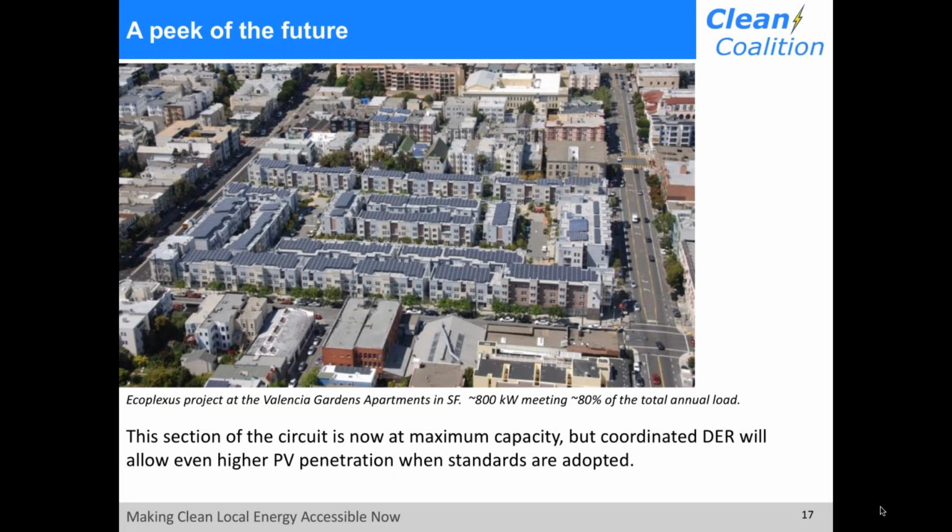Under a separate CEC grant contract, we are independently arranging installation of energy storage on the same circuit that will mitigate grid impacts of the existing solar and allow more PV to be installed on that circuit without upgrades. The storage will also offset its costs by providing grid services. Current limitations on interconnection standards created significant barriers, however. Despite the fact that the batteries are being installed to demonstrate that they can greatly improve hosting capacity, utility studies assume that they will have the opposite effect until certified methods of guaranteeing the operational profile are accepted by the utility. Next slide.